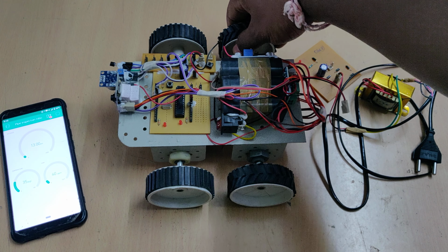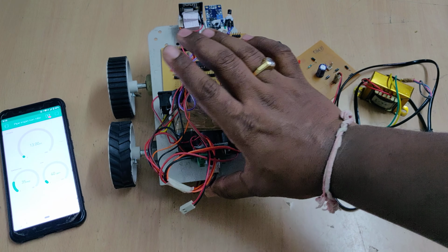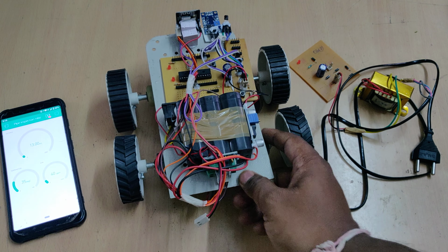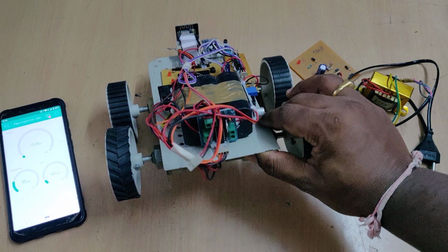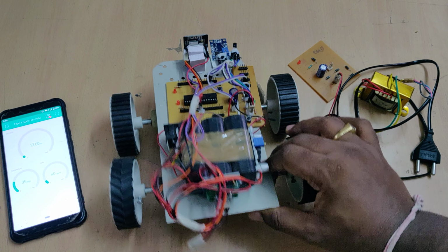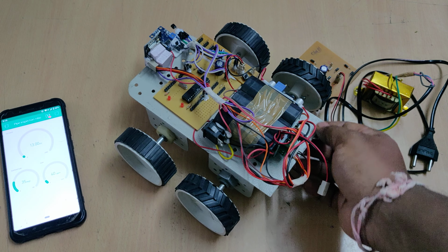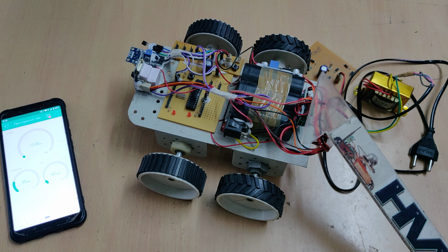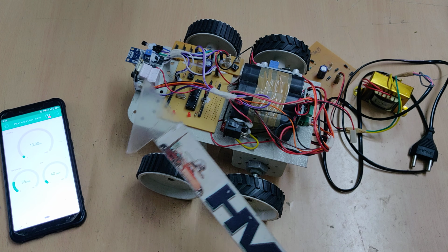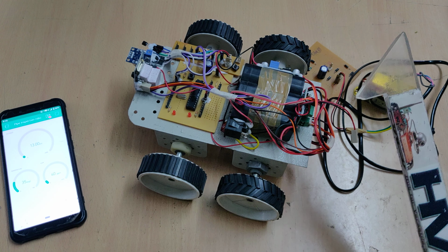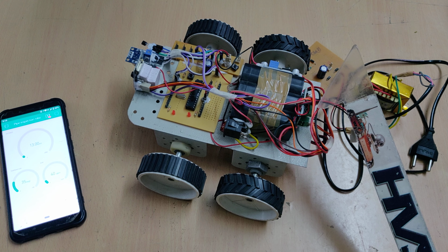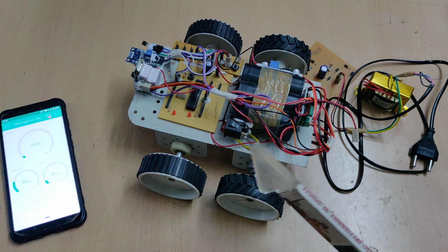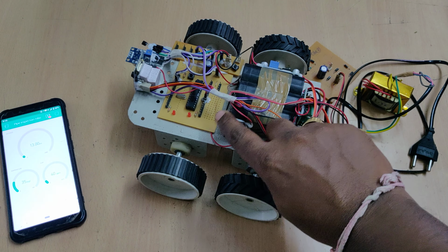And to control the directions of the DC motors, we place the L293D motor driver, which will take the signal inputs from our ESP32 camera directly, and based on that we can control the directions of the two DC motors. As we need a 12 volt power supply to control the DC motors, for that purpose only we are making use of the L293D motor driver. So the ESP32 camera will give the signal to the L293D motor driver, and the L293D motor driver will provide the 12 volt power supply to change the direction of the DC motor directly. And this is the main on off switch.